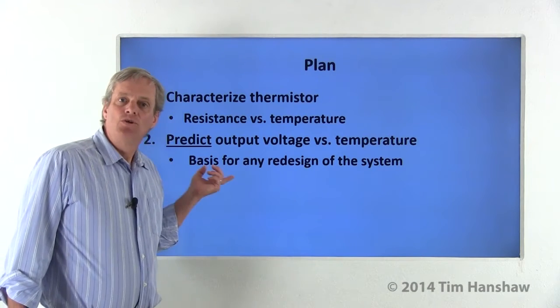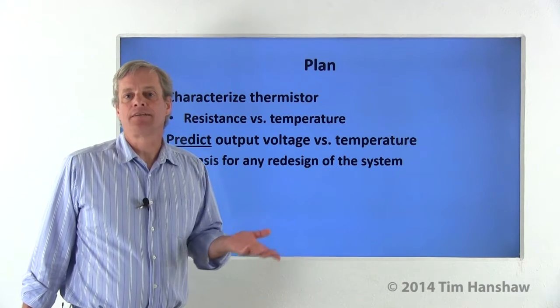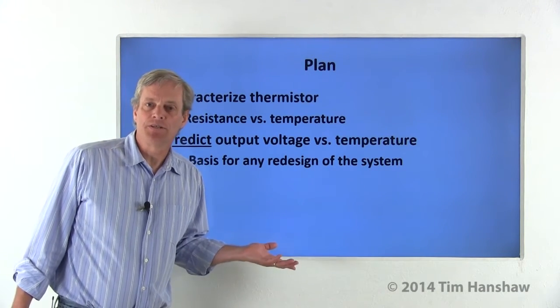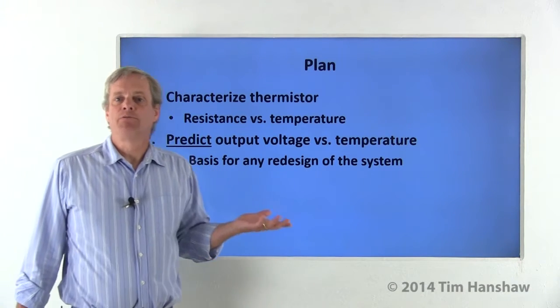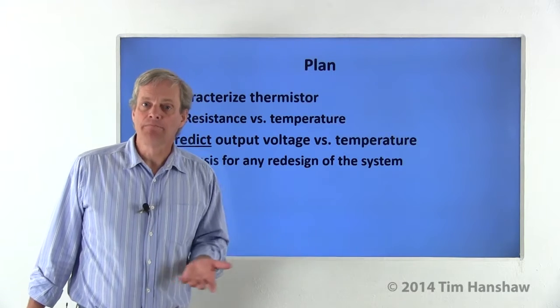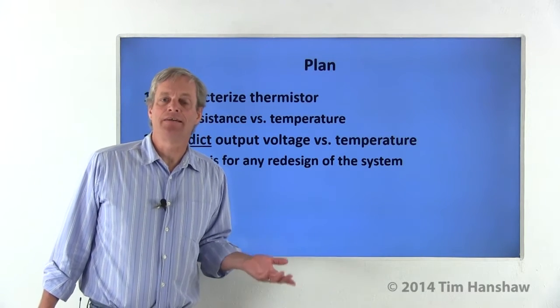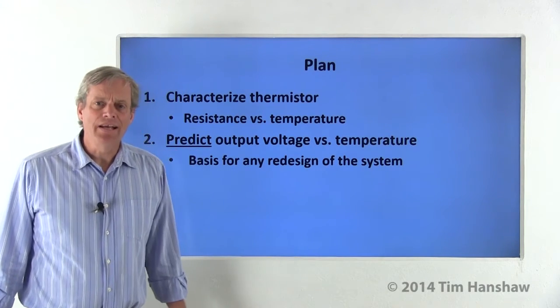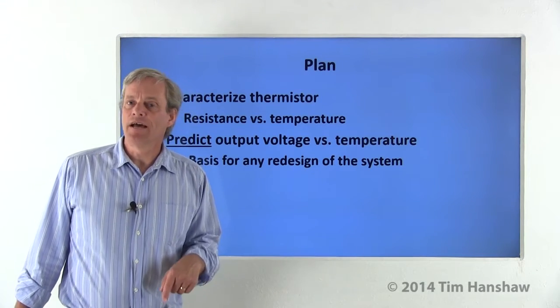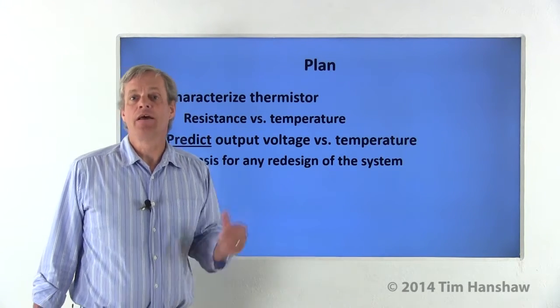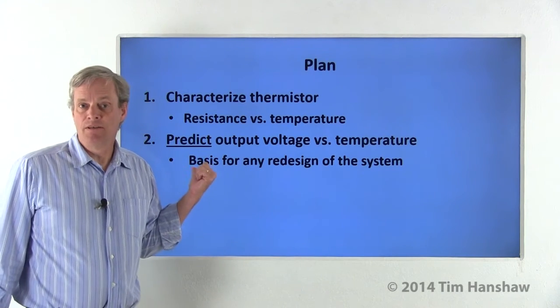Secondly, you'll want to mathematically predict the behavior of the temperature measurement system, which was the voltage divider on the previous slide. The ability to predict the behavior of the system and compare your expectations to the data is very important. You may not need this information to determine the sensitivity, but if a redesign of the system ever becomes necessary, this is the tool that you'll need to be able to do that.